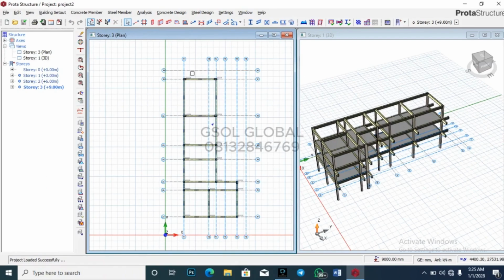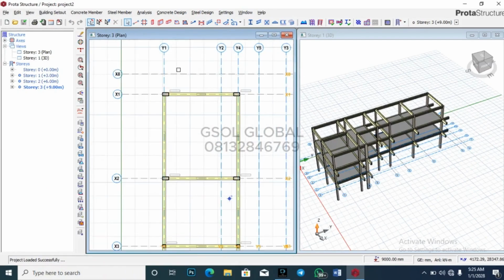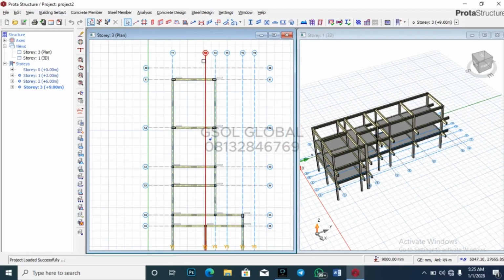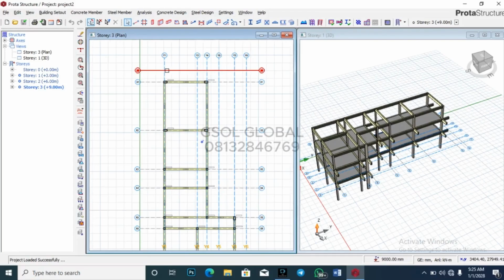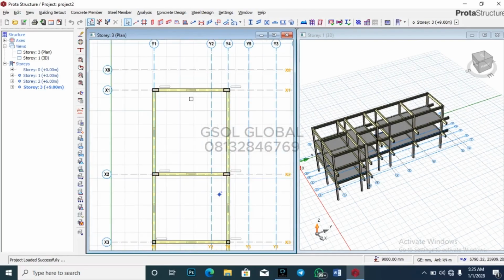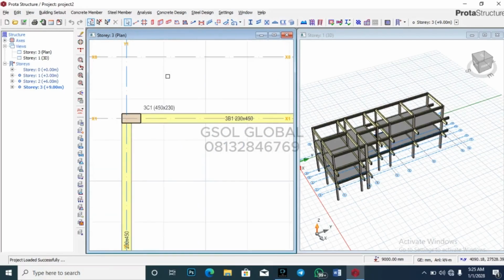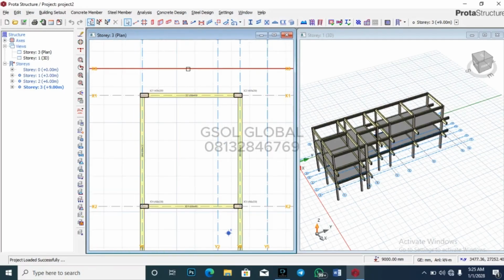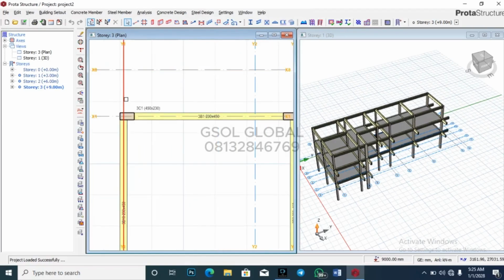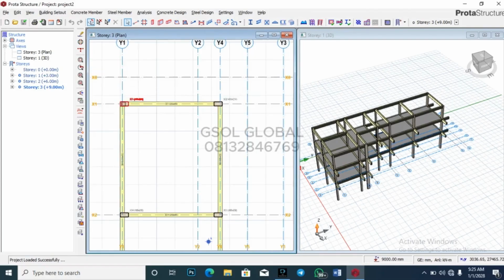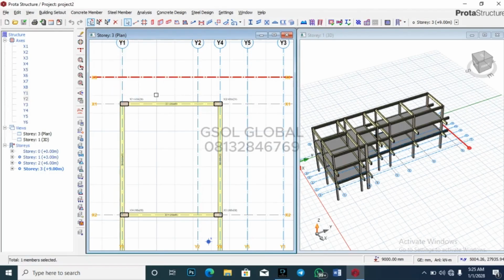What I'm going to be doing here right now is something very easy, right? We're going to place our slab in this particular cantilever slab around the part where we have it in this particular structure. So I want to give you a hint that will help us correct some mistakes that might come up in future perspective. So this is it here. As long as you have a rectangle enclosed by grid lines, like this one here, if I want to place my cantilever slab here, then it will just be spanning from this point to this point, this point to this point.